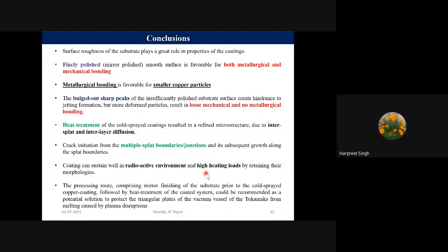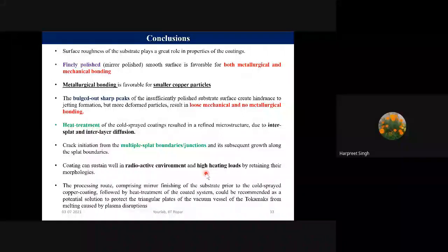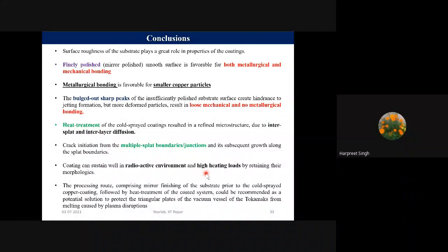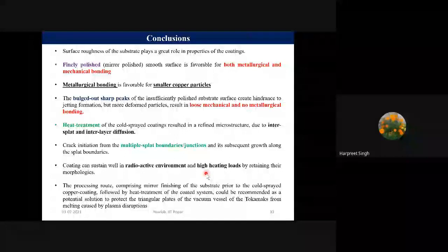Because these coatings are to be used in radioactive environments and so on, he even did radioactivity tests of the exposure of these coatings in some lab in Delhi, and we can see that the coatings sustained very well. And once we exposed them to these radiation loads, we saw them through SEM again to establish that nothing has happened to these materials.